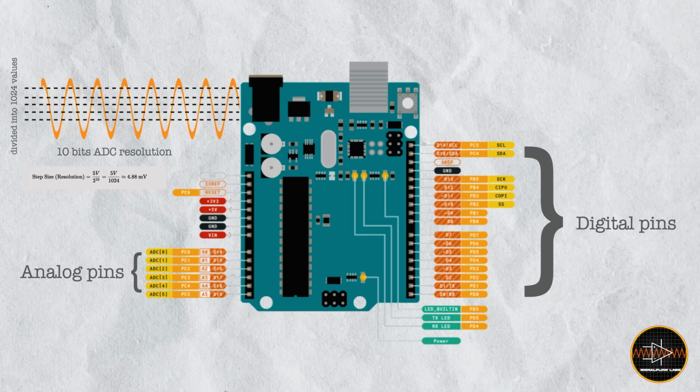So in that way you can basically divide and get the exact value on your screen, on your Arduino, as you can see on the screen. And as it's a 10-bit ADC converter that's available on Arduino Uno, you get from 0 to 1023. If it was 12-bit or 8-bit, you'll get different values based on that.